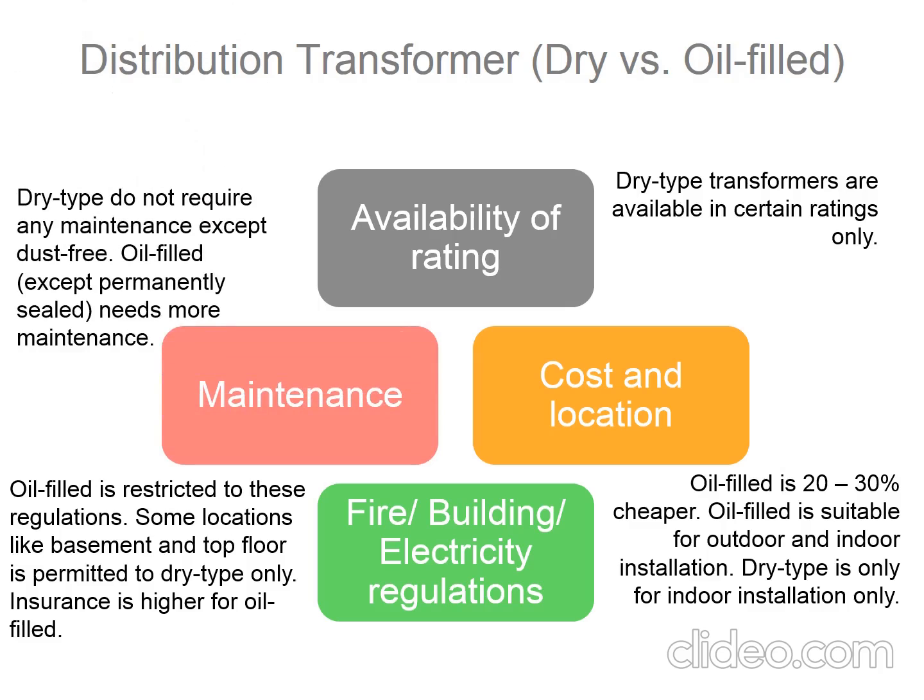For maintenance, dry type does not require any maintenance except keeping it dust free. But oil filled, except permanently sealed, needs more maintenance because the characteristics of the oil will change.